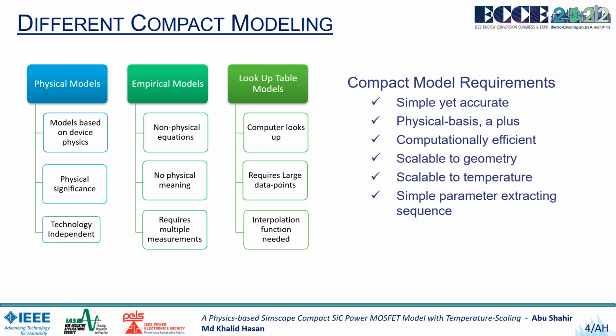Therefore, a compact model should be simple yet accurate. If there is a physical basis, it is a great advantage. It should be computationally efficient, scalable to geometry and temperature, and there should be a simple parameter extraction sequence.